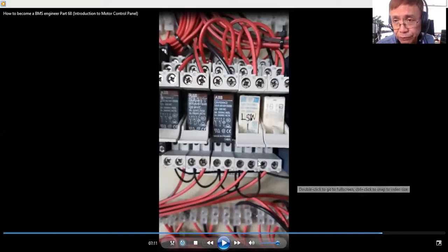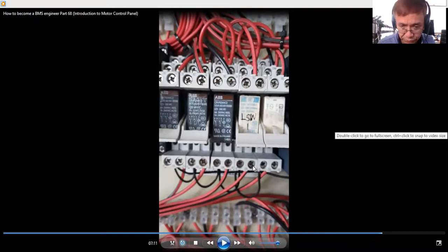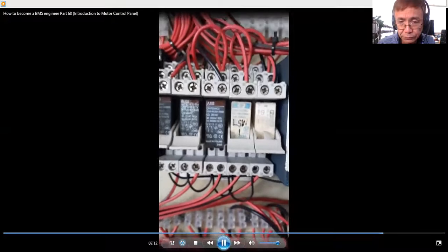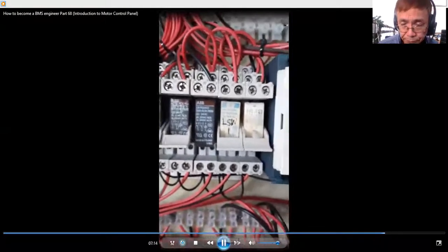So you need a volt-free contact coming from the motor control. So I'm using this miniature relay to give the DDC the volt-free contacts like the run status from the MCC, the trip status, and the hand-off-auto status, from MCC to DDC. So this is the use of this miniature relay that I'm using for my automatic operation.